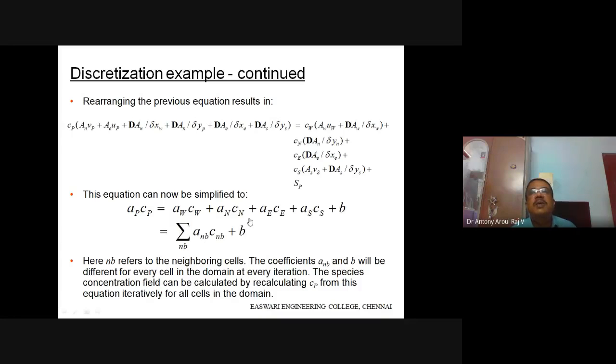So in a three-dimensional equation, the equation is not only connected with the east, west, north, south, it is also connected front to back. So here I have to add east, west, north, south, then front to back also. Then I am going to have 6 terms on the right hand side. It is connected throughout. So that means a three-dimensional domain, that is a volume.